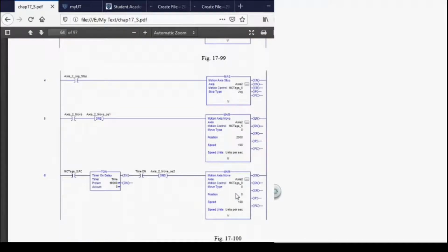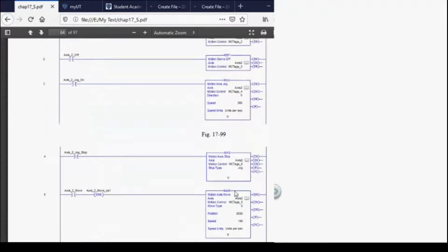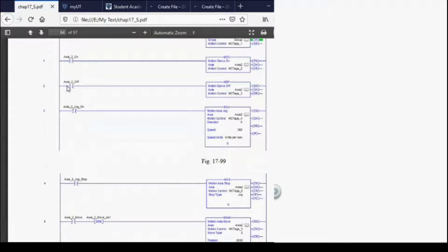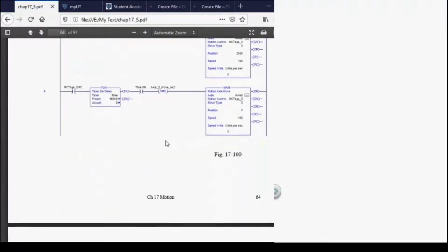Again, this was written kind of as a starter program, but the point is this: with this one, there's no inputs, so you cannot get an input directly, a switch input. But what you can do here is you can right click and toggle that bit, and that'll execute that instruction. So that's how you would test each of these functions.